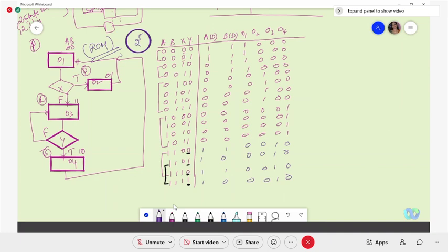Maybe for the ROM approach, smaller systems or systems with a small number of states will be preferred. For more complex ones, you need to go for either mux or one hot, as we were saying. Even in mux, if it exceeds 32 states, you have to split that. In one hot, if you take more states, the cost of the design will go up. So we may not think of this one hot approach.